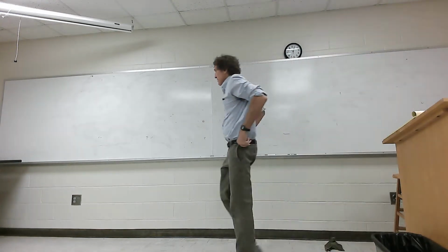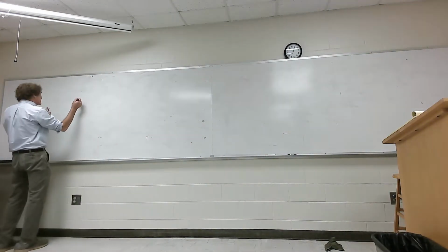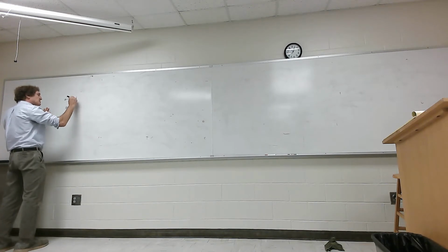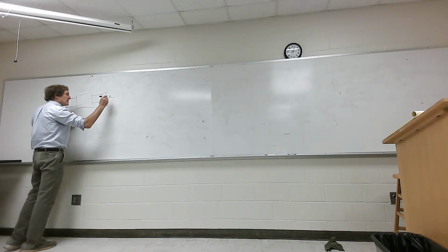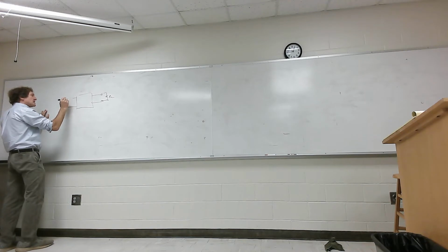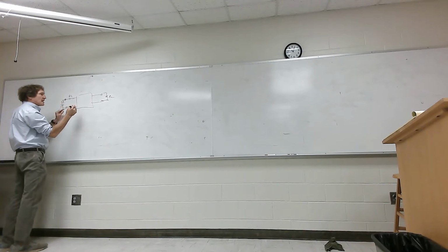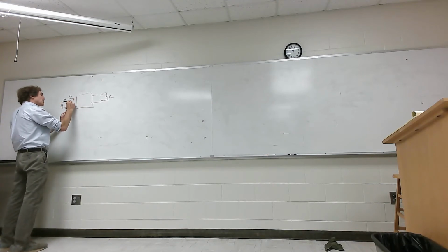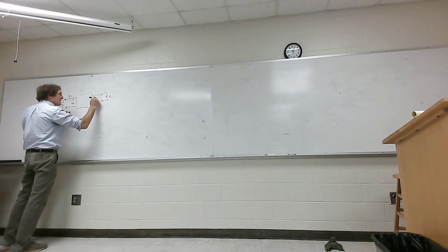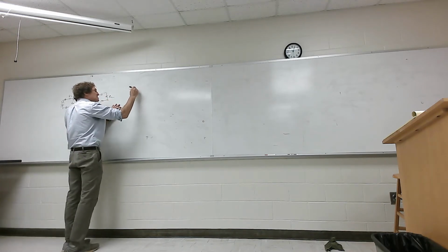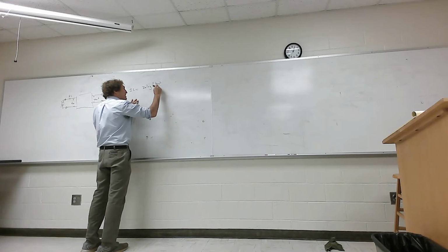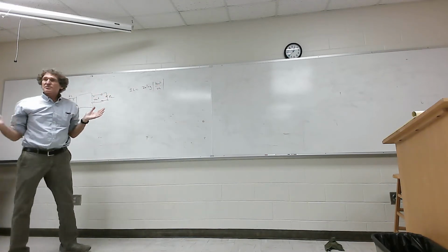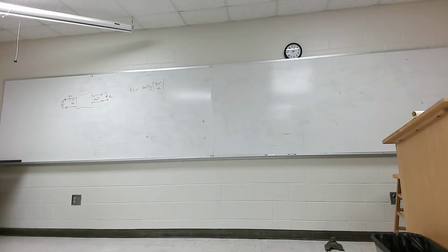I'm going to start this way. When we talk about a filter in general, you're talking about a block diagram that looks like this. I should have done this the first time. You're going to have some load resistance, RL, and a source resistance, RS, and then you're going to have your voltage here. This would be the input, the in, and this would be the output, the out. When you talk about the insertion loss, that's really just 20 times the log of the magnitude of V out over V in. Now I can put it in terms of S parameters, but I'm trying to be as simple as possible about this. I think everybody appreciates that, right?